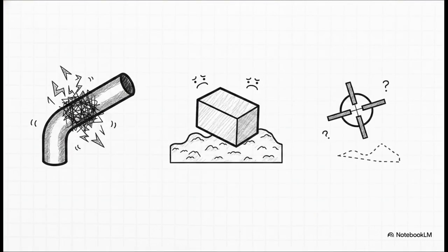Other common drafting pitfalls include selecting unstable datums, failing to include basic dimensions on the drawing, or picking completely imaginary points in space to measure from. Sometimes designers use a true position callout just for the sake of using GD&T, without even checking if the manufacturing process, like tube bending or casting, can actually achieve it. You really have to apply tolerances where they matter for function, not just because the CAD software lets you.